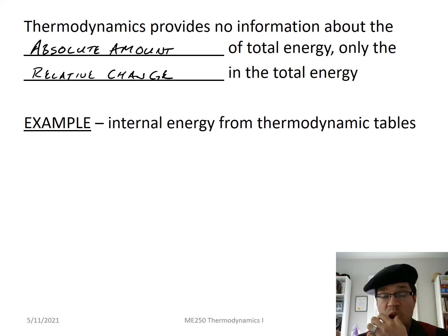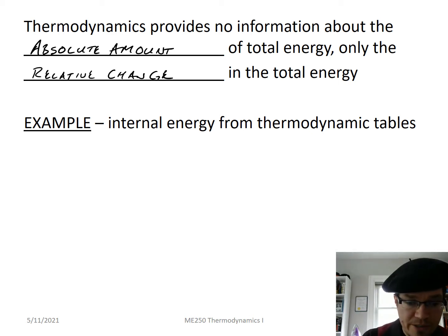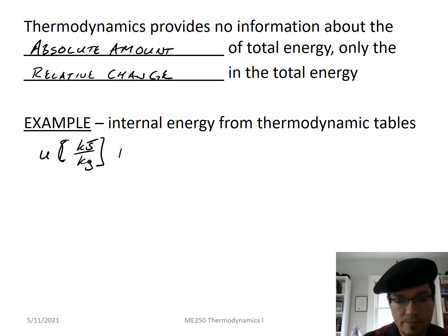So absolute 0 temperature is the lowest temperature you can achieve, and at that point all molecular motion of normal simple gases stops. So that is a nice hard reference to zero energy for those gases, but that's not actually where we say you have zero energy. So if you go into the tables, and we're going to teach you how to do that in the next couple of weeks, if you go into these tables of internal energy versus temperature versus pressure for different materials, etc., you will find that the internal energy, U, measured as always as kilojoules per kilogram for liquid water,